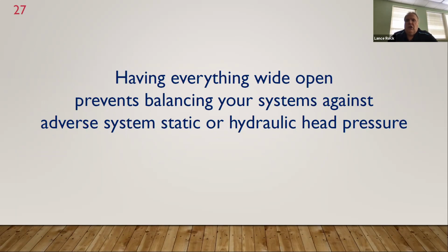This prevents your systems from having the adverse effect of system static and hydraulic head pressure. We don't want to start balancing a system where all the dampers or hydronic valves are partially or fully closed, because we want to have the least amount of pressure against the system while we increase flow. You're going to see a slide. Pressure and flow together is extremely expensive. A fan with no pressure barely costs any money to operate. A fan with no airflow but high pressure is, again, very cheap to operate. But combined, that's when you start spending money, same as with pumps.